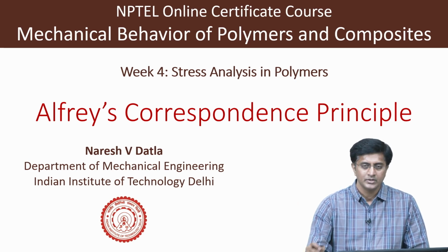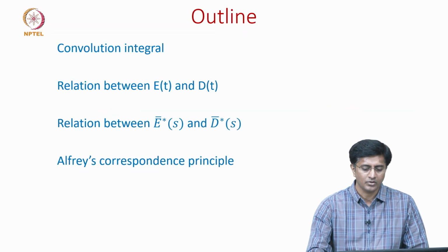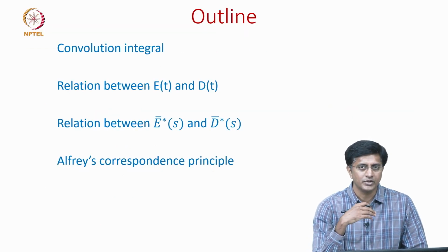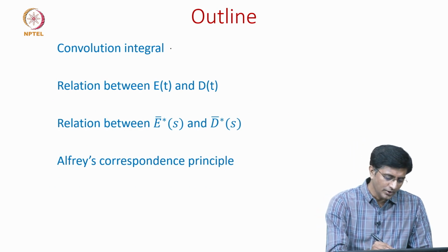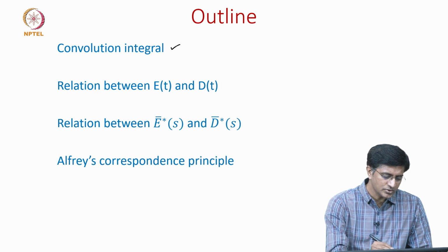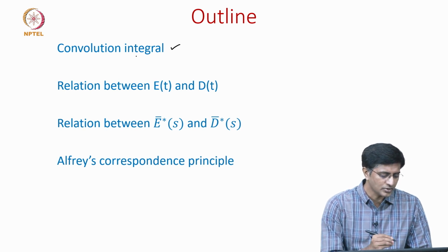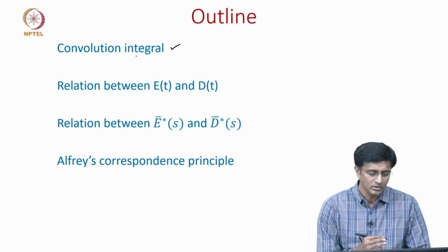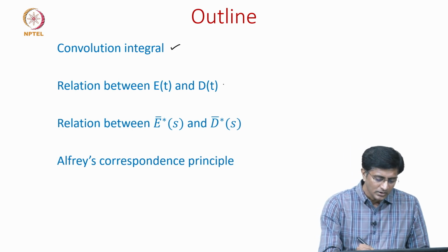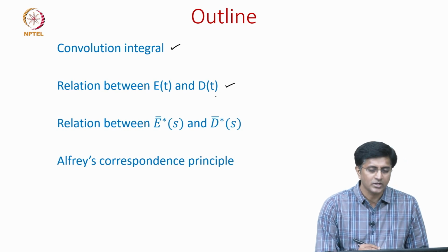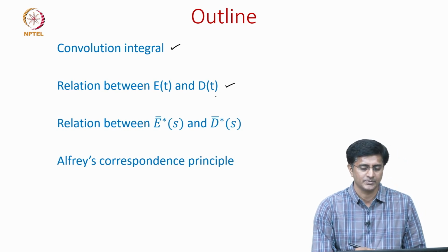Okay. So, for this we will build on what we discussed in the previous video, where we discussed the Boltzmann integrals. In addition to these Boltzmann integrals, we also need to know one other concept called the convolution integral, which helps us bring a relation between the relaxation modulus and the creep compliance.